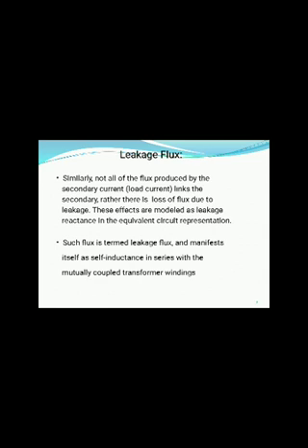Such flux is termed leakage flux and manifests itself as a self-inductance in series with the mutually coupled transformer windings.